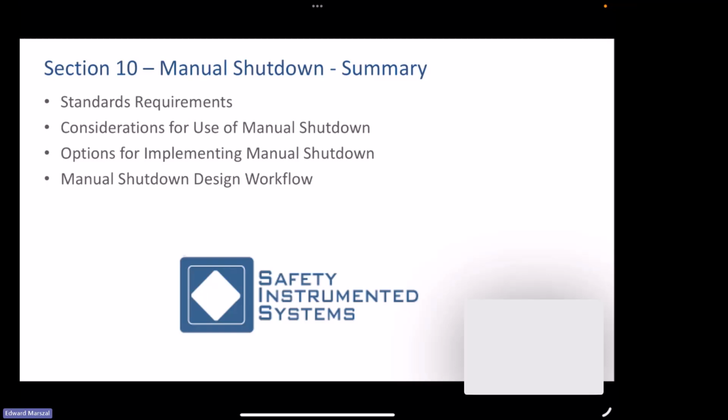when you have an alarm or a manual activation, they are part of a protection layer. So an alarm is part of a protection layer. Manually closing a valve is part of a protection layer. How much credit did your LOPA take for that protection layer? Probably 0.1. But you don't get to use that entire 0.1 PFD for that alarm or for that manual activation.